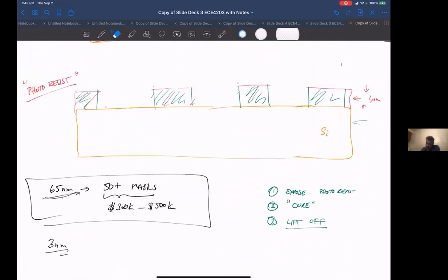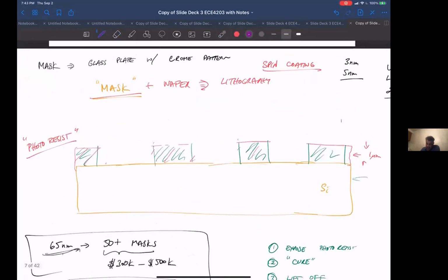Now, if I put this in an ion implanter and implant the whole wafer, say, for the sake of discussion, with N+, where there is the hardened photoresist, the N+ ions don't have enough energy to go through to the silicon. But where there is no hardened photoresist, they'll go into the silicon. So what I'll end up with is N+ in these regions.